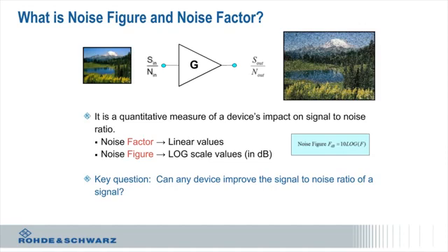Because the nice thing for dBs is you actually do everything by adding and subtracting. So where you have something like an amplifier that has a gain of 30 dB, that's a factor of 1,000. So instead of multiplying things by 1,000, you're just going to add 30. Anyways, I spoke of that in a previous presentation, so you can review that. We have those on video.